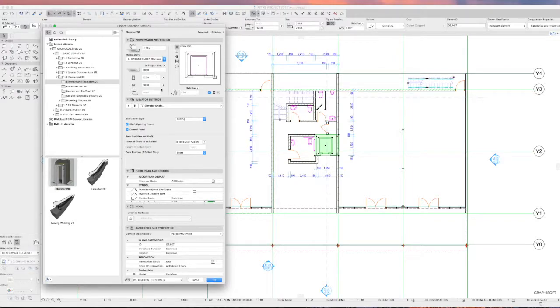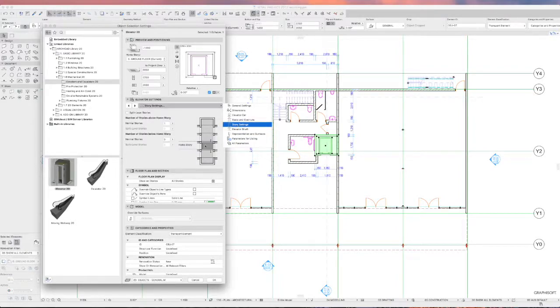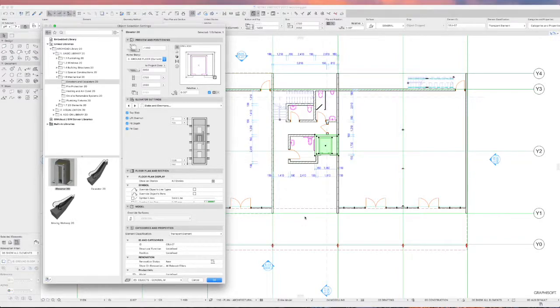And probably also you need to take into consideration slabs and overruns. See, I've got a total of 1300 plus 150 here. So we want to set the bottom of this arrangement to negative 1450 from ground floor level. That way it'll bring the opening, the first floor level, or the lowest landing, down at ground floor. If we set it up to 1300 plus 150, that gives me 1450 here for the bottom of the elevator from ground floor. So if we click OK to all of that,